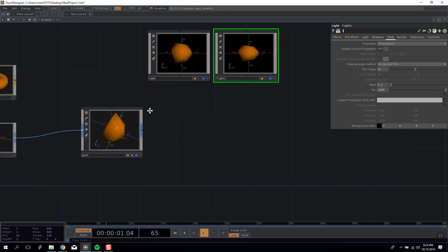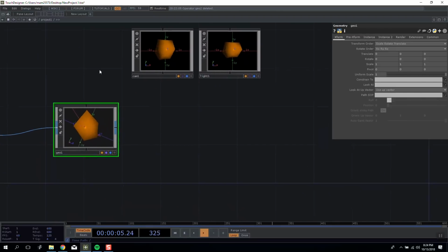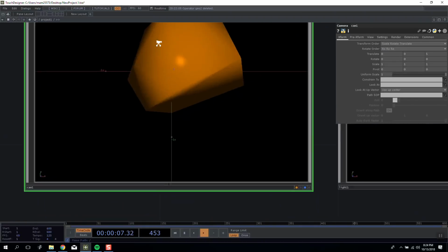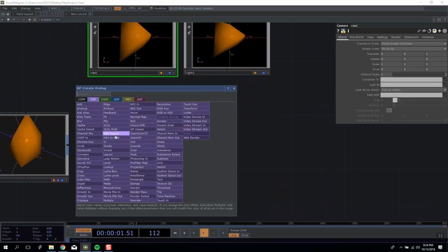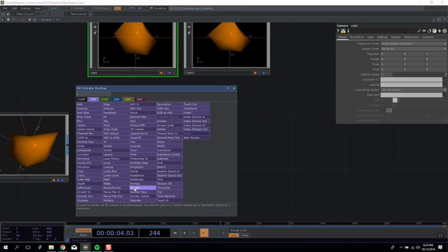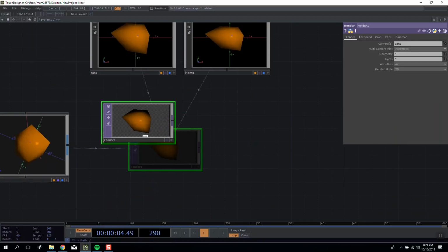So the final piece of the puzzle we need is we have world geometry that we can now manipulate and look at through a camera, but we need somewhere to capture this camera. So we introduce a special render top. And as you can see by the description, it's used to render all 3D scenes in Touchdesigner. You give a camera object and a geometry object at a minimum, and we have both of these. So let's give it a render.